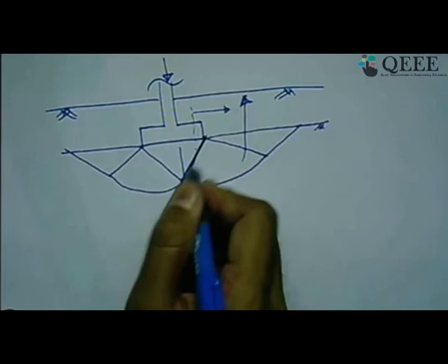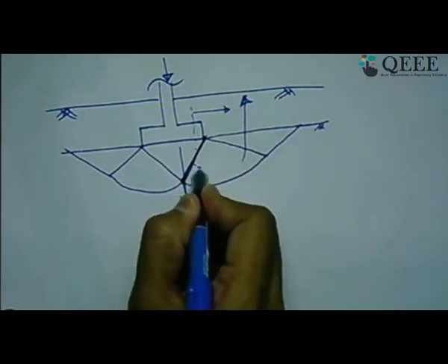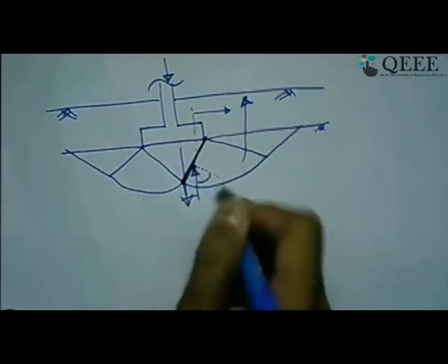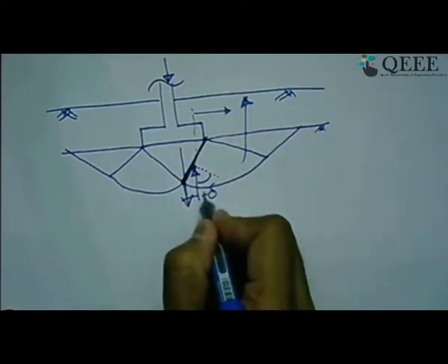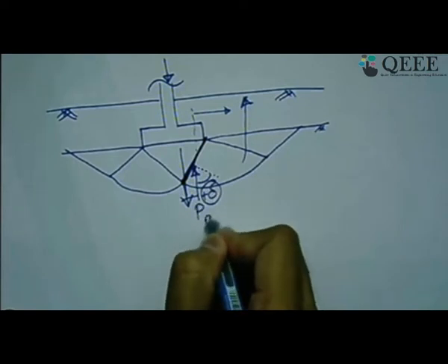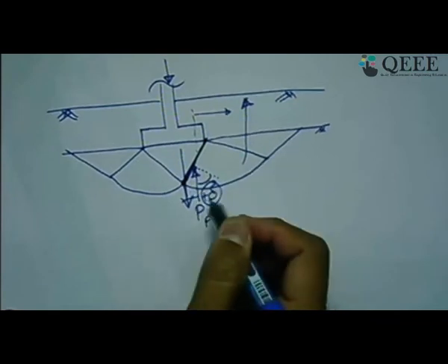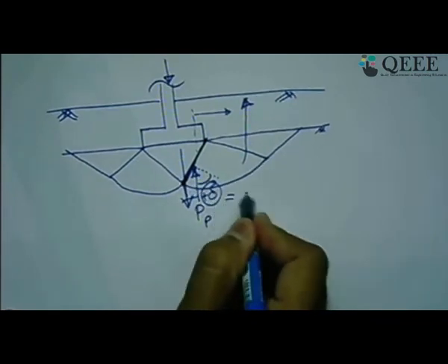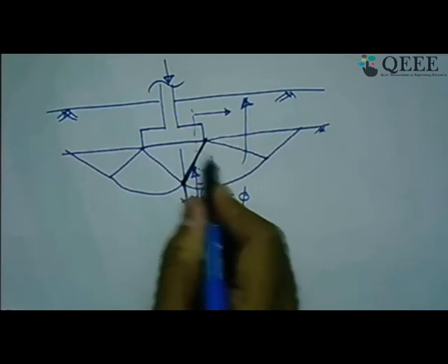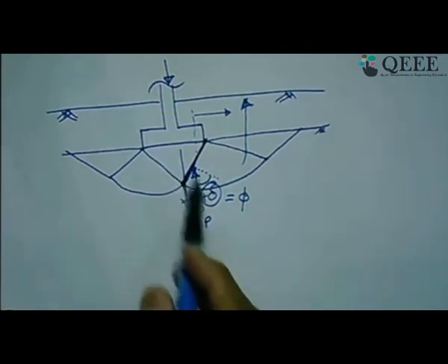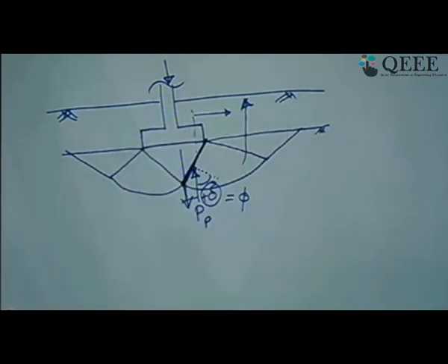So if you take the normal to this wall, we mentioned that this is the direction of delta, with positive delta, at which the passive earth pressure works. And as this is an imaginary wall, in Terzaghi's theory this positive delta is nothing but the value of phi, because both are the same media, the same soil. That is how the positive wall friction angle of passive earth pressure theory is nothing but the application to the bearing capacity theory.